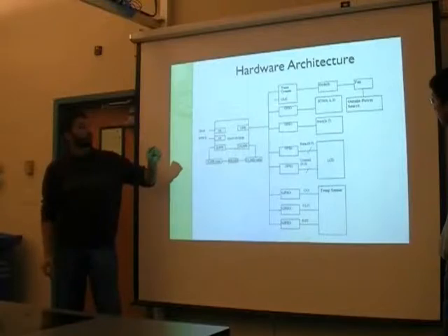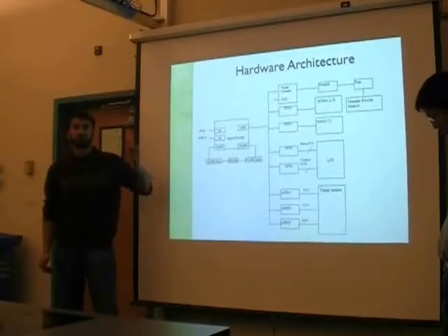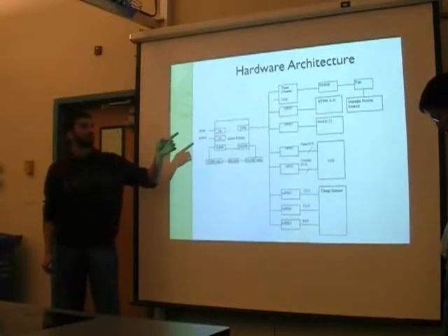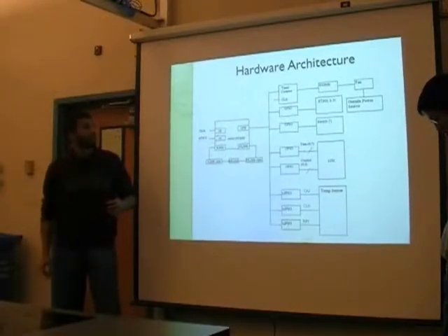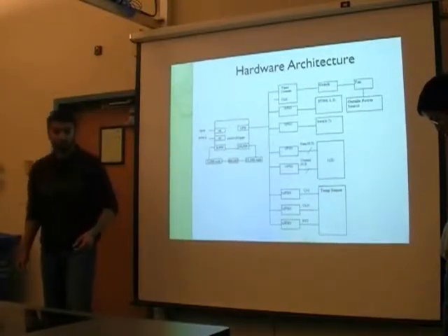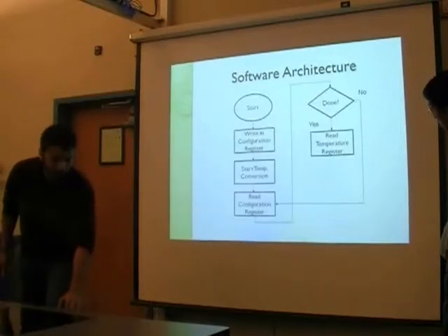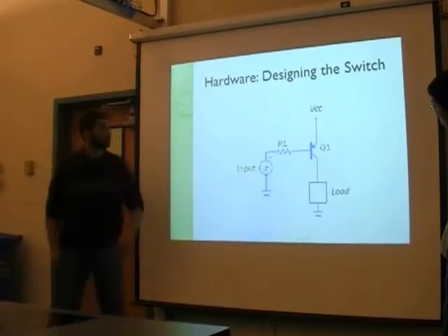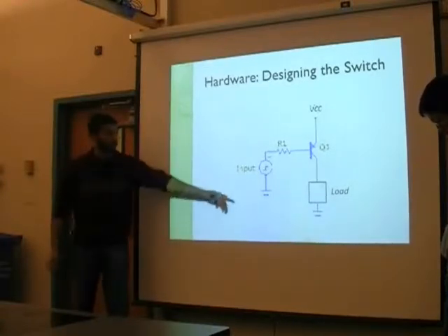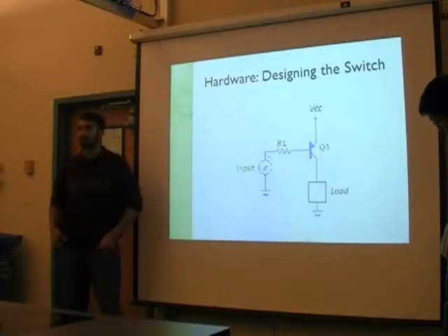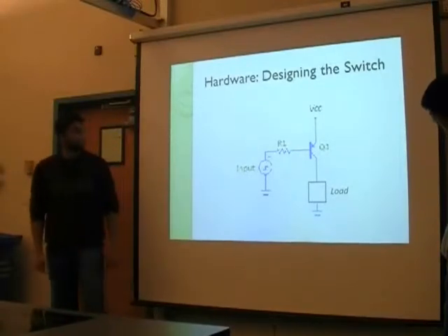We also output the square wave straight from the timer counter. We did not use the DAC, and we built a small switch in between. We built a pretty simple PNP BJT switch for our pulse modulation. The load is our fan, which is a linear load.